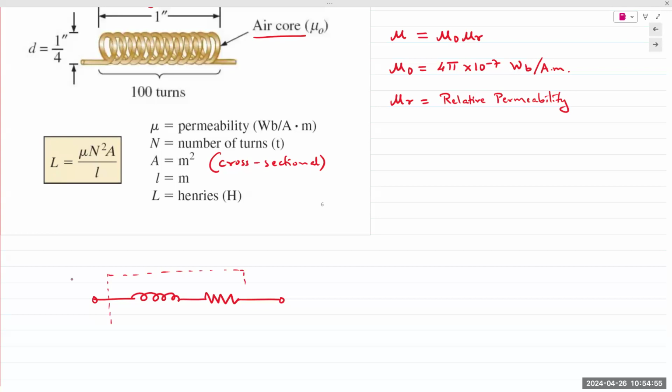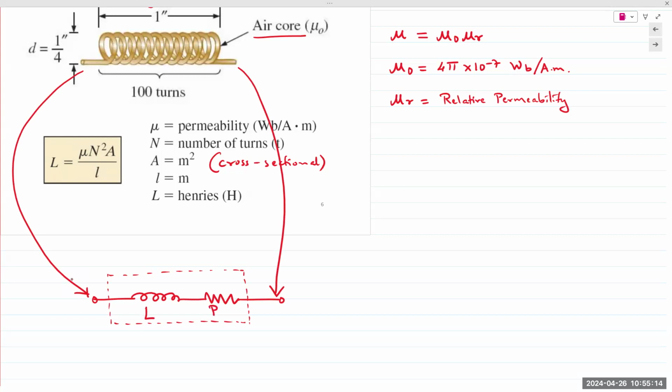Okay, we cannot separate this out. We can measure it, we can manipulate it, but we cannot separate it out. And so if you measure from this end to this end, that represents that entire curve. The inductor portion is represented as L, and the resistive portion is represented again as RL. But this time RL is not load resistor, it is the inductor resistance.